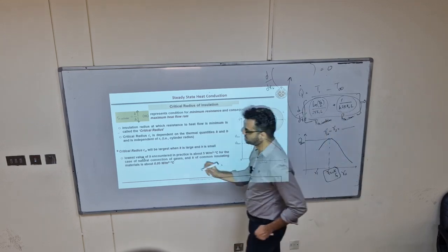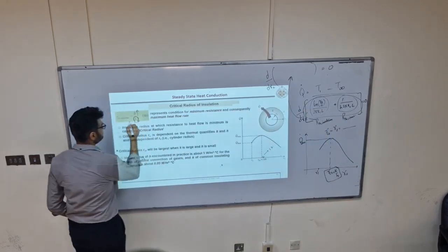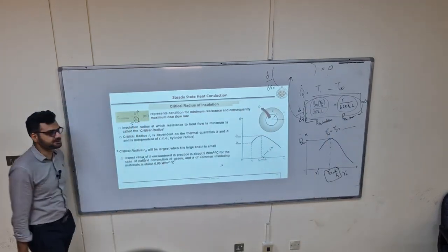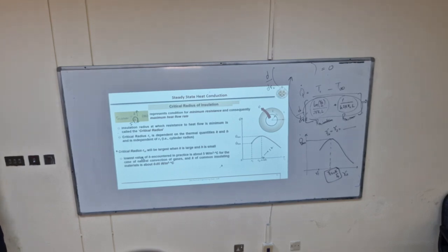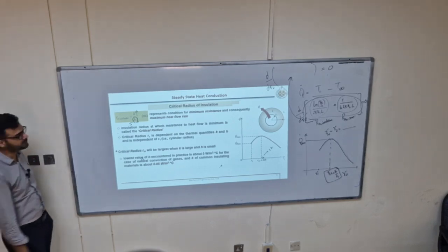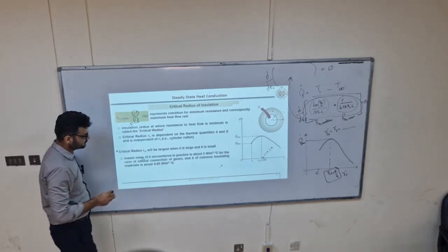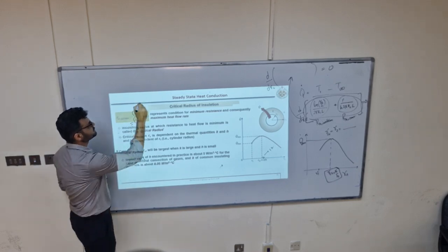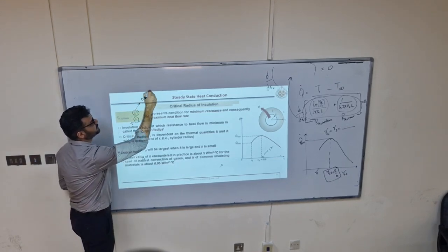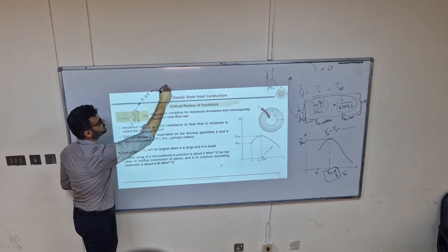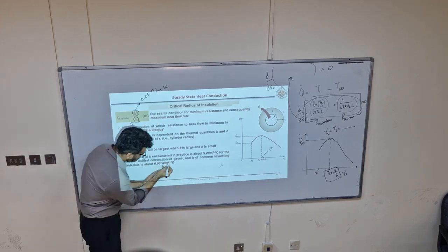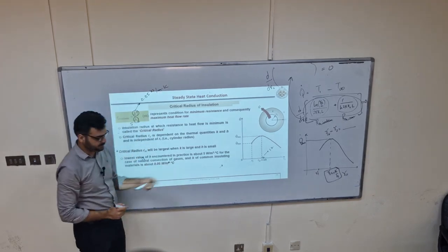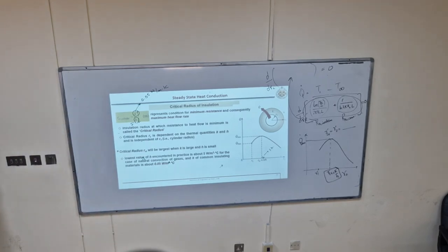Let me say this is 5 for natural convection in normal ambient air. And k for insulation, he is taking a value of 0.05, some insulation, 0.05 watts per meter per Kelvin. Here it's a mistake, it's watts per meter per Kelvin or Celsius.